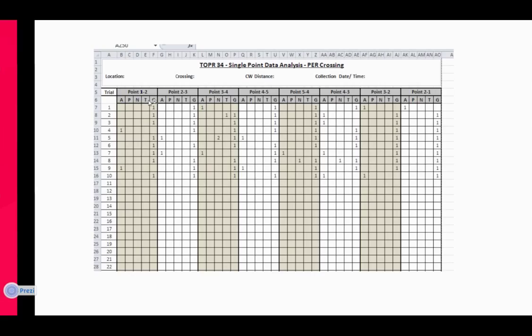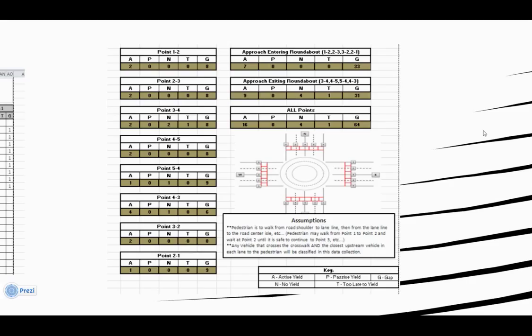The fourth would be the wall inspection cycle. How often are these walls inspected? Are different walls inspected at different times? Are different walls inspected more frequently than others? Some of the agencies would have, every 6 months, an inspection by just a maintenance worker that would drive by and make sure there's nothing drastically wrong. And then every 2 years, a qualified inspector would go in and look at the wall top to bottom, and that would be the major inspection for that wall.